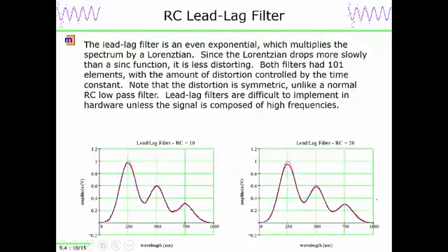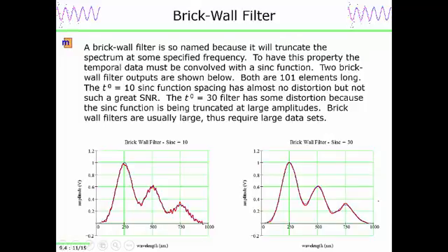So the Brickwall filter, I think it's useful to see what these things do in practice to get to know what an appropriate filter might be. The Brickwall filter does a good job of reducing distortion and suppressing low frequency noise, but you really see this ringing here is all from the remaining noise that's still present. And it's quite obvious where it abruptly stops and you have this frequency content. This ringing is pretty clear. If you make that longer, then you can do a very good job of suppressing it.